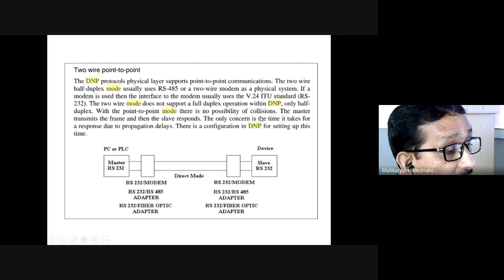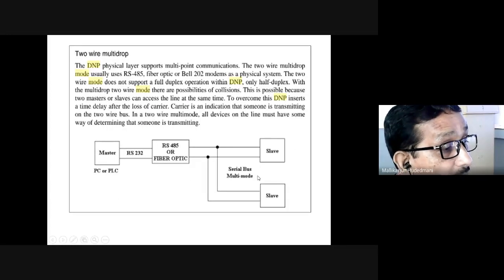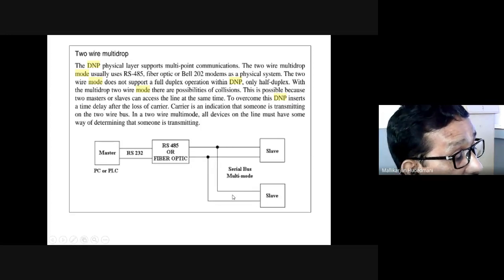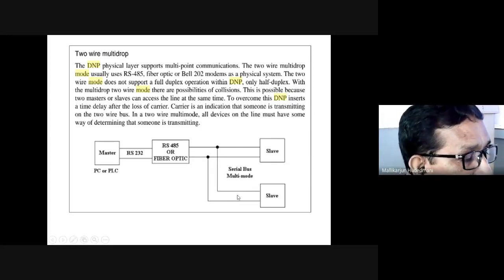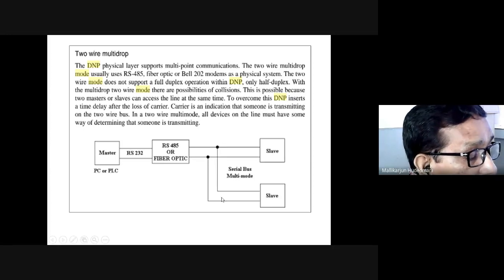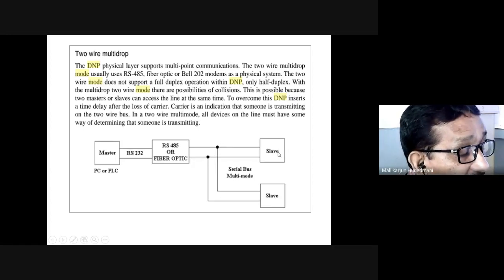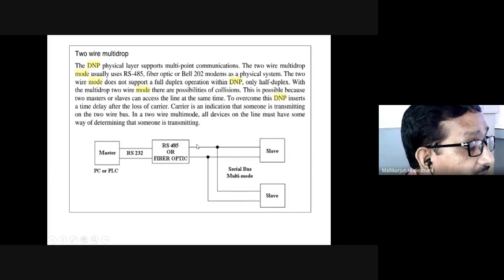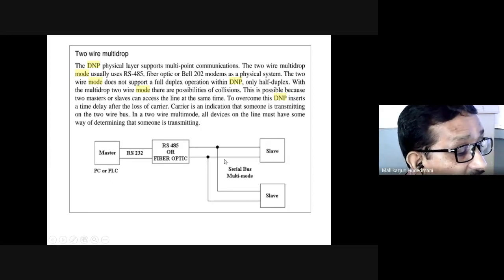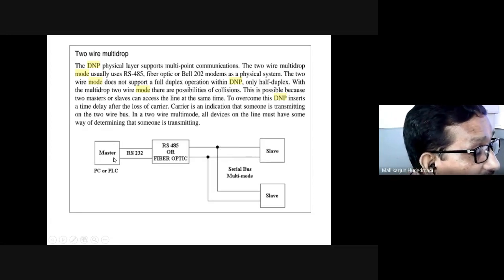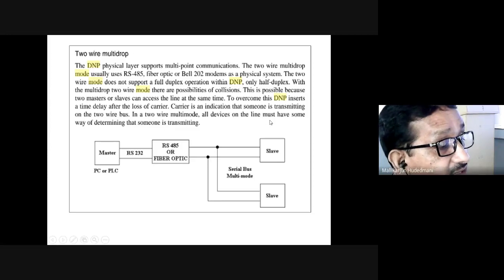But here, as it is multi-drop, each device is ready to receive the information on its turn, and there could be an error. Any slave could respond wrongly. The tag which is sent by mistake may be acknowledged by any of the devices, they may respond unduly, and the master may get wrong information from this, or it will start acting as a malfunctioning device. Those will have collisions in the channel. Those collisions will propagate to the master with the erroneous data. That's how these collisions are possible.